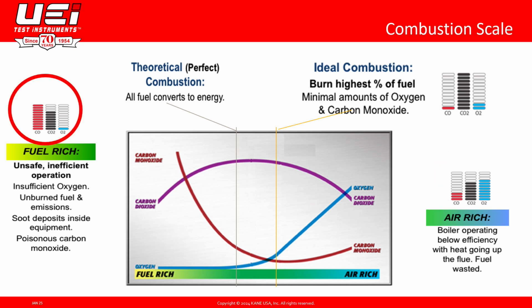And we can see that our combustion gases change a little bit. We wind up with higher levels of CO. Our CO2 levels are going to drop, but our oxygen levels go up way high. On the converse side, though, we could wind up in a situation that is fuel-rich. And fuel-rich, again, is exactly what you think it is. It's too much fuel and not enough oxygen being burnt. And when that happens, one, we wind up with some really dirty equipment. And it doesn't take a whole lot of sooting on equipment to ruin that efficiency. The other thing, though, that we might notice is that our levels of CO go up quite considerably.